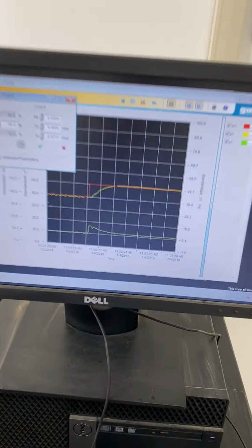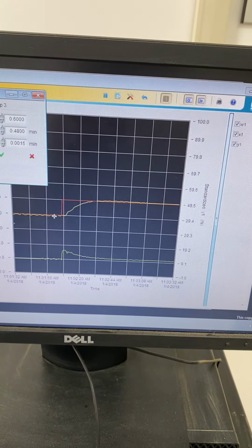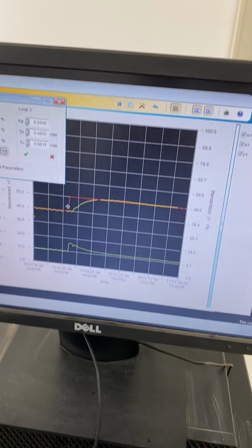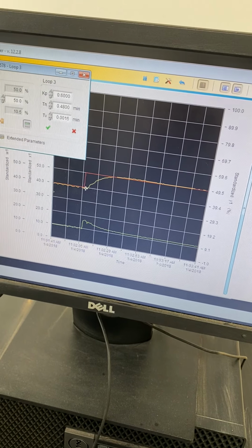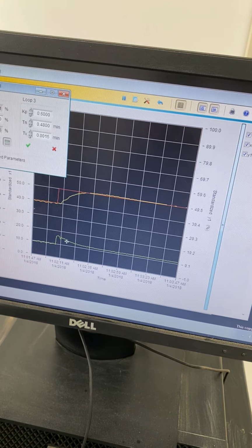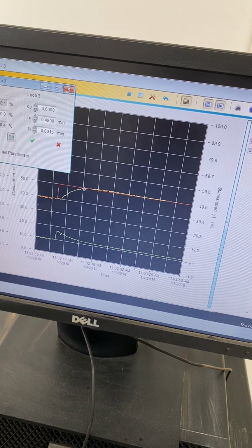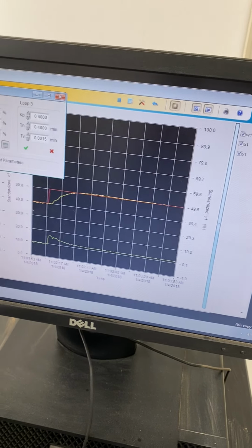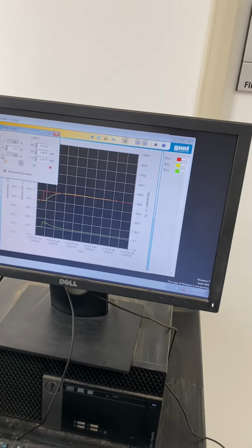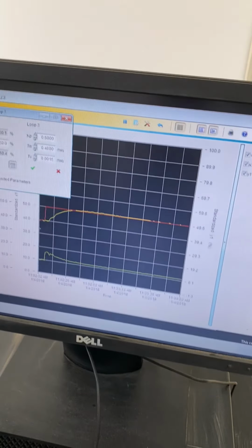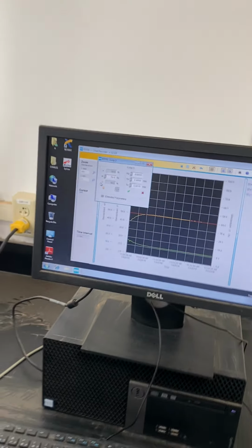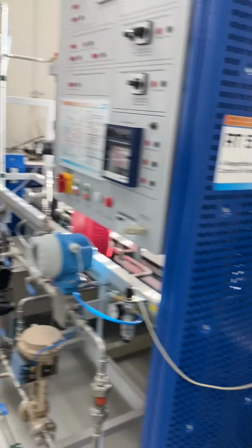Okay, of course, as you can see now, right after the set point has been changed from 40 to 50%, again I've got a change in the output because of the error. Notice the error here at this point, which is the difference between the PV, the yellow line, and the red line. So it immediately increases the output signal, and it continues to measure and calculate the proper response or action in terms of the output signal to the pump. Okay. You can see right now at 50% it is getting stable, reaching a new steady state operating point at 50%.